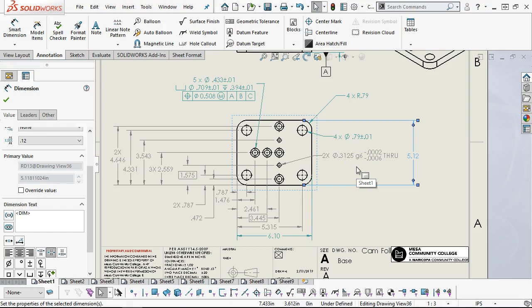What I'm mostly used to doing is just giving it the four decimal places and saying plus nothing minus 1,000. If we end up in that area, that pin is going to press. What we haven't decided yet is, is this a steel? Is this a stainless steel? Or a plain carbon, 1018, 1020? Is it aluminum plate? Each of those materials is also going to affect some of these decisions that we're making as far as this tolerance zone.